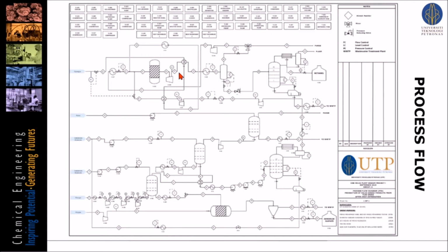However, this stream will be a gas-liquid mixture before it enters a phase separator to separate the unreacted carbon dioxide and hydrogen from the methanol and water. The methanol and water that leave the bottom of the separator will enter a distillation column. The methanol will be separated from the water by its boiling point, so methanol will become our next value-added product from pure CO2. Now we will move on to the instrumentation and control, where I will give a brief